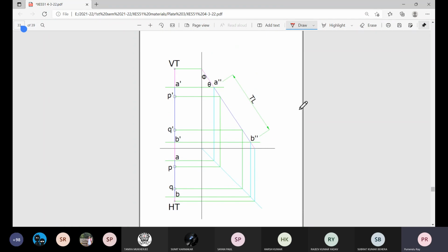Just remember, and if you cannot remember it properly, take a set square, hold it in such a position that it is perpendicular to both HP and VP. That is, the line which is the diagonal of that set square is parallel to the pictorial plane. And it is a simple case. Now one thing you can do, just take a screenshot of this page. And this is that special orientation of the line AB parallel to pictorial plane. And from those basic information, you can draw those 3D views, which will give you almost all information about this.